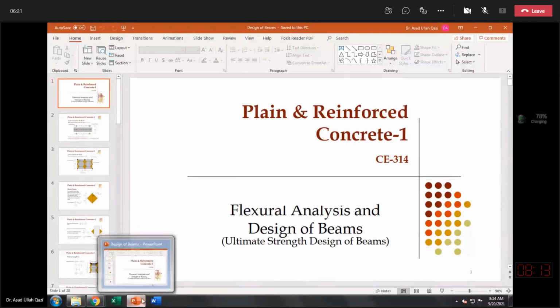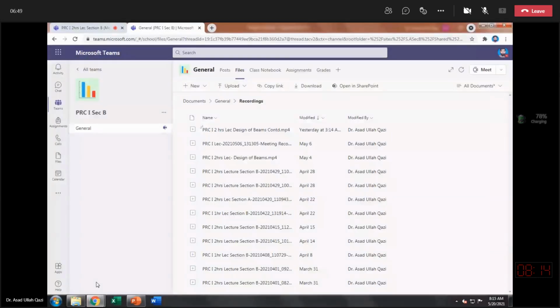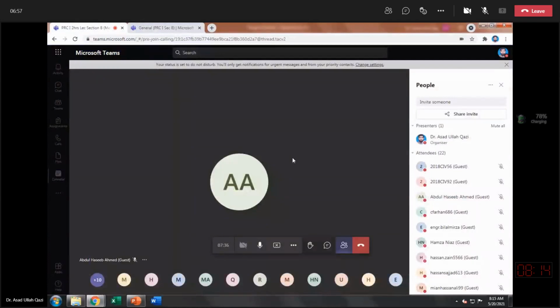And one actual slab system in which beams are present, we want to solve that kind of problem, that a room slab and that slab has beams. So how much load will travel from the slab to the beam, and then after getting uniformly distributed load on the beam, the design as you are familiar with direct design by calculating rho of tension control on the reinforced beam and then designing it accordingly will be repeated.